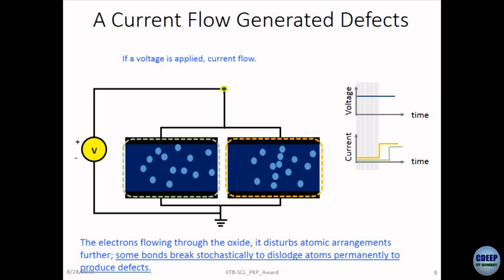Now, if an atom gets displaced, for example, there's a point defect, current will not flow. Why? Because there is no way for the current to cross the river, right? How will you flow it? Well, the defects get generated randomly, so it keeps on building, and then at some point a bunch of defects align and the current can essentially go from one electrode to the other.